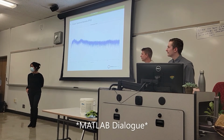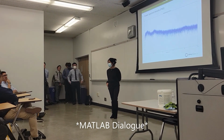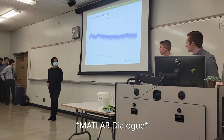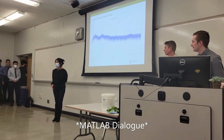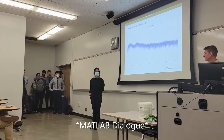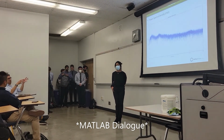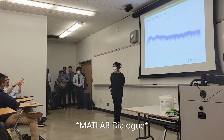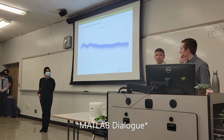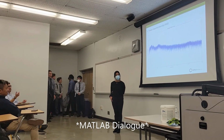I think my actual question is, do you happen to know what the FFT window was? The window? The window, yeah. Often you look at PSDs and it almost looks like a line, like a Bode magnitude plot. Sometimes it looks like this if your FFT window is really high. This looks like a fuzzy white line. I think the reason it's doing that is because it's got so many data points. Remember this is frequency, right? So it's not temporal. But it has to do with that window.